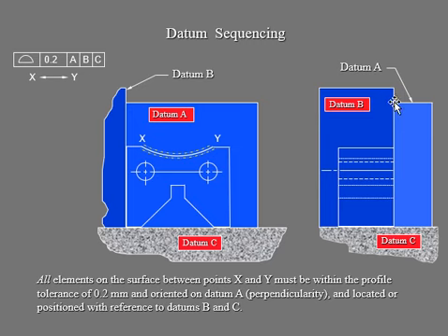Meaning this perpendicularity is in reference to this surface and also that surface, because if you extend it, it will go to here. Don't forget the change of the view. Okay, that's the side view, and this is your front view. So that's why when you write the datum A, it is right here, it can be seen like that in the back. And this one also, of course, is right here.